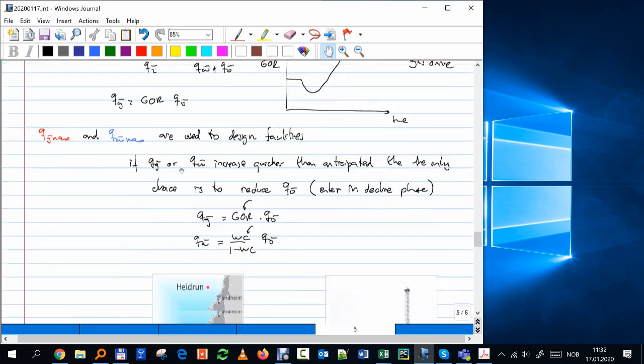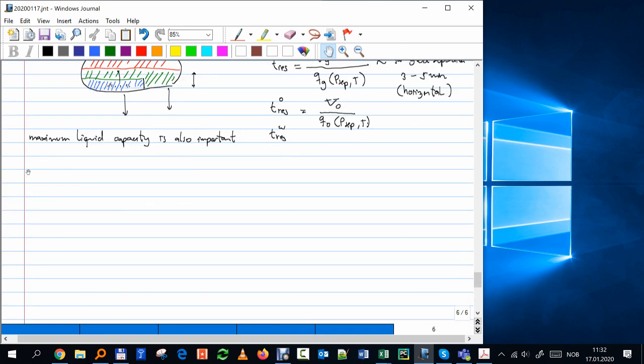So let's put that comment here. We say that bottlenecking, for example, water injectors. Water injector plugging. If that's the case, I have to evaluate a method to frack. If I'm afraid it will break or contaminate something, then I don't do fracking, but I probably just re-drill a new injector, which is expensive.